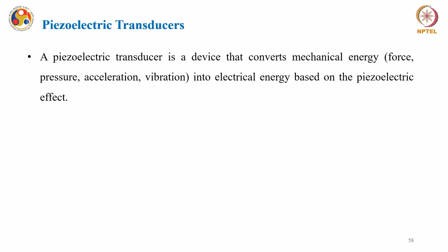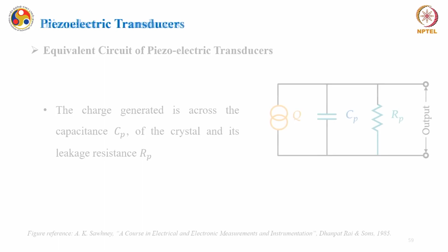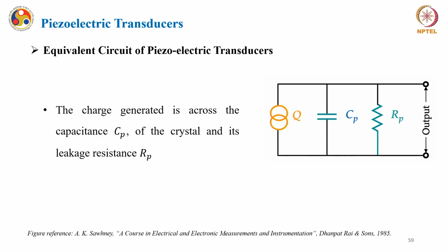Then piezoelectric transducer, we have seen in detail how these devices can convert mechanical energy, including all kinds of mechanical inputs like forces, pressure, acceleration, vibration, into a certain form of electrical energy, based on the piezoelectric effect. We have also derived a piezoelectric transducer equivalent circuit, and we have seen that it is a kind of charge generation device, with a capacitor and resistor in parallel, and the output was taken across this leakage resistance RP.